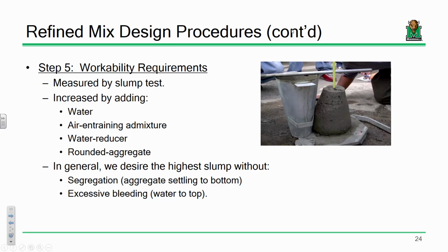And we didn't do moisture corrections because we were just doing a quick dry run just to make sure all the equipment was working and all that. And because we didn't do moisture corrections, and because we probably had negative free moisture inside our aggregates, nudge, nudge, wink, wink, what ended up happening was the amount of water that we put in our mix was a lot less than it should have been.